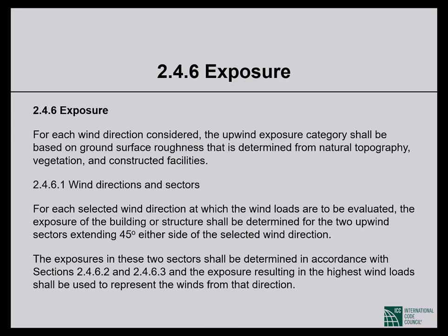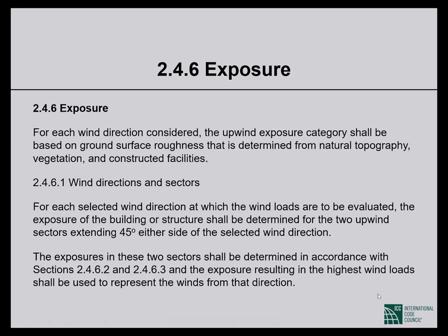Exposure categories: there was a time when exposure categories used to be directly defined. Not anymore. We now have definitions for roughness categories, and then the exposure categories are defined in terms of the roughness categories. So let us look at all of that. This is kind of complicated stuff, I will warn you. For each wind region considered, the upwind exposure category shall be based on, well, let me not go into that.